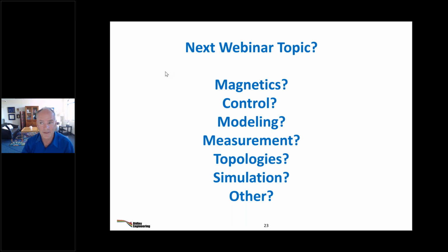You'll just simulate it in SPICE with an emulator for the network analyzer. But current mode control, yeah. It's not like you can't do a half bridge with current mode. You can do AC current mode in a half bridge. So it's a deep topic. It really is. That's why we didn't do too much on the control here.